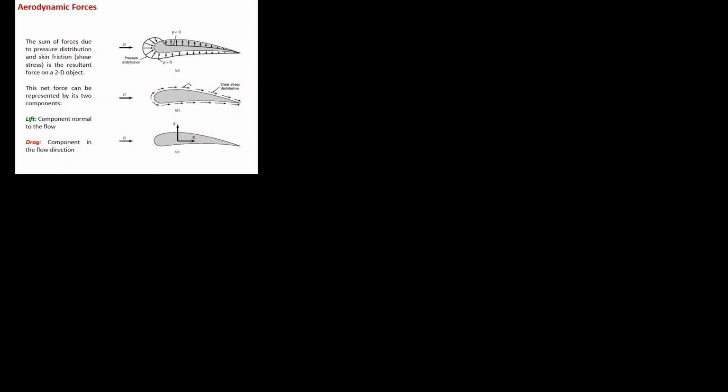Because if the high pressure was on top and low pressure was on bottom, then you were pushing your wing down, right? But lift is pushing your wing up. So the pressure difference, yes. Low is on top and high is on bottom. Let me put this, you have negative pressure distribution on top and positive pressure distribution on the bottom. Okay, so that's a more accurate description. Okay, that's good.